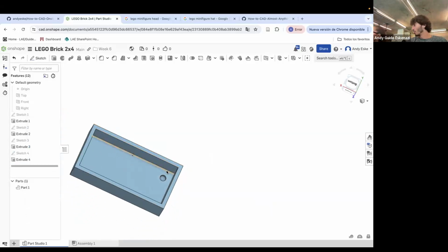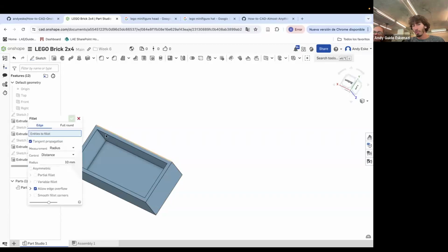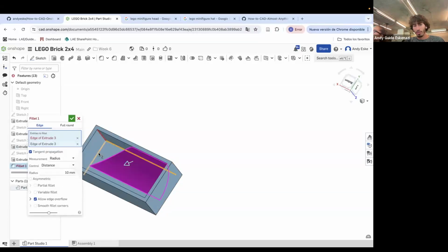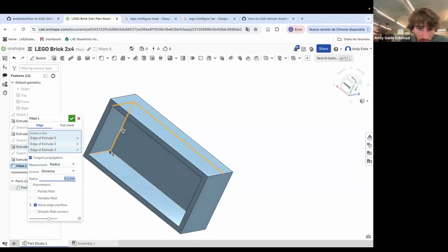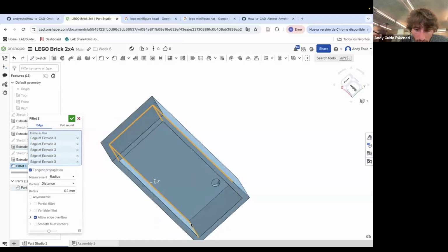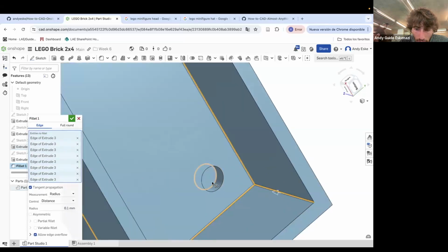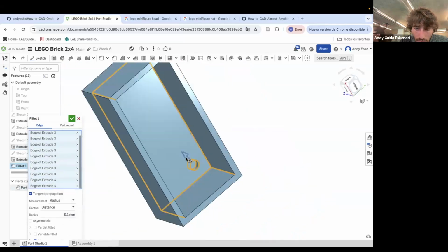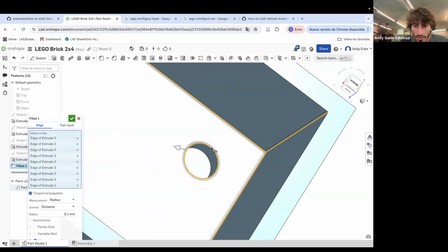Yeah, so we're gonna make this look almost identical to like these bricks. So then obviously there's no sharp edges. So you probably want to fillet all of the different parts. But just a tiny amount, like 0.1 millimeters is enough in here. Perhaps a little bit more, but I should make these in a different one. Very good.